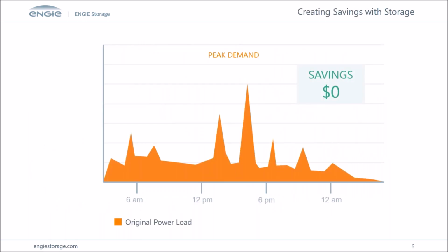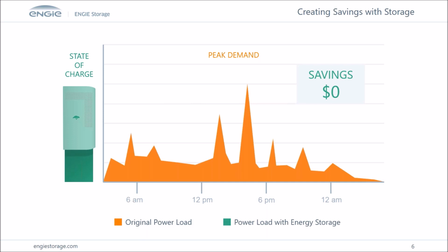And for those of you who are not sure about peak demand, I'll show you exactly what our system does pretty much every day on a site. This happens to be a load profile on a 15-minute window of one of our customers. We install an energy storage system that is connected to the main building meter. So the intelligent system will understand and see exactly what's happening with the building load at any given second. And at the beginning of each billing period, it automatically predicts and learns to adjust what the maximum demand level is that the utility wants to see.